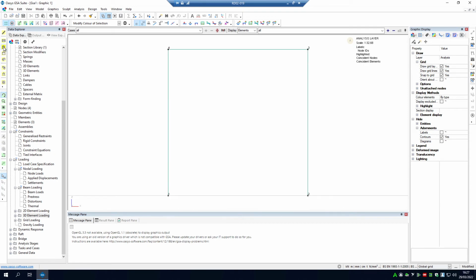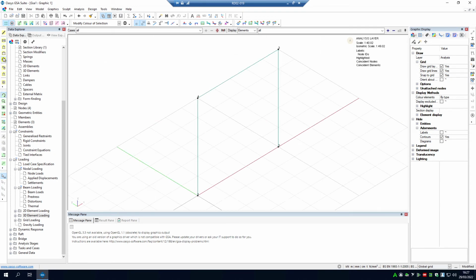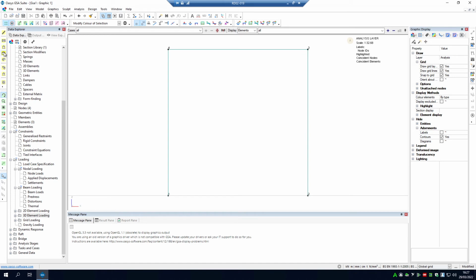These are all your view buttons for different angles. So if we click on the Y elevation, that gives us into the Y axis. So we know that this is node 1, 4, 3, and 2, because I applied it 1, 2, 3, 4. Label restraints. So click on that, it tells you what nodes are restrained. So we know at node 1 we applied a fixed restraint, and at node 2 we applied a pin constraint. So they have shown up here.